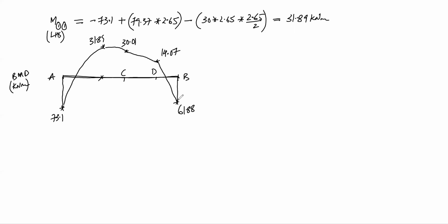So this is the bending moment diagram, and these are the significant points. Above the reference is positive and below the reference is negative. If required, we can calculate the points of contraflexure by considering moment at that point and differentiating it with respect to x and considering it as 0 to find the distance x.